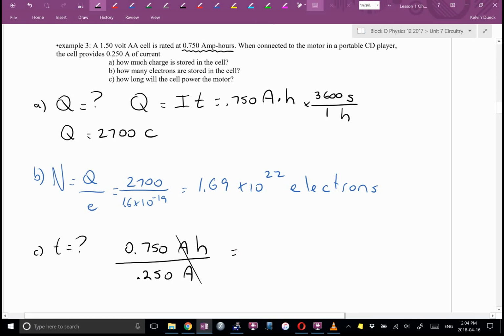3, I think. Bang on. Yeah. And that's where amp hours are handy. They let you, through some reasonably simple mathematics, make a pretty good guess as to how long your device will last. As an example, if you're an RVer and you know how many amps your refrigerator draws, you know how long you can run it off the battery before you better start your vehicle up and recharge the battery for a while. Yeah? Is it okay to give our answer in hours? Or are we gonna times by 3,600? 10,800? Or am I off? Yes.